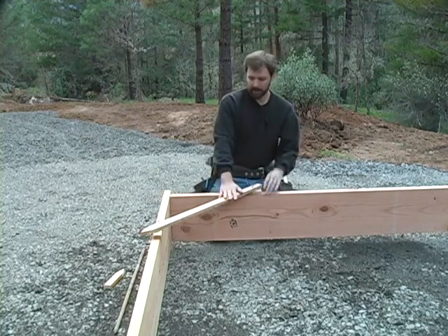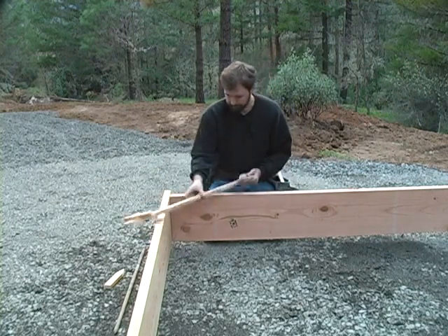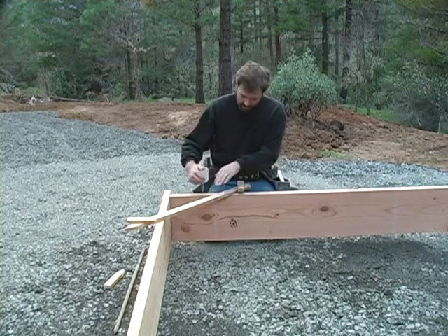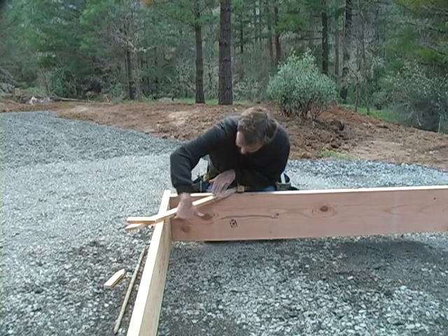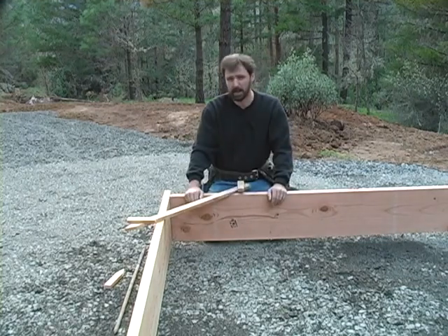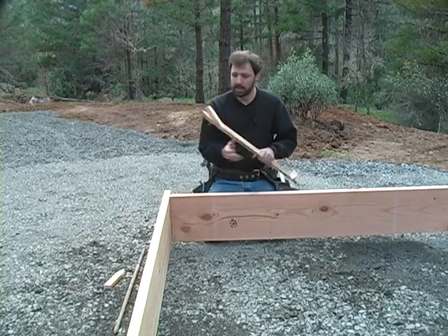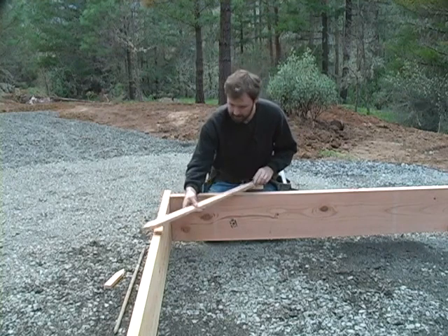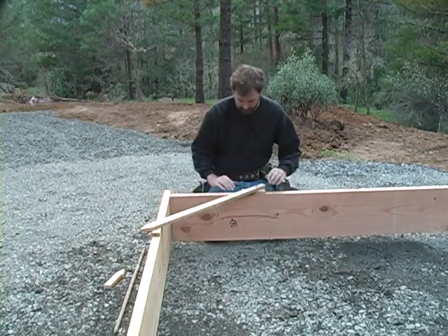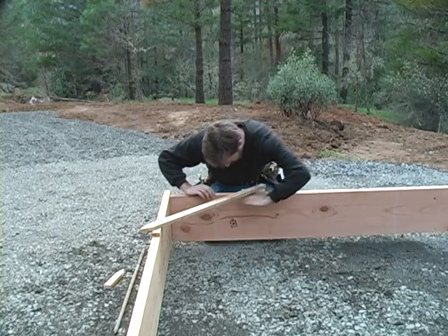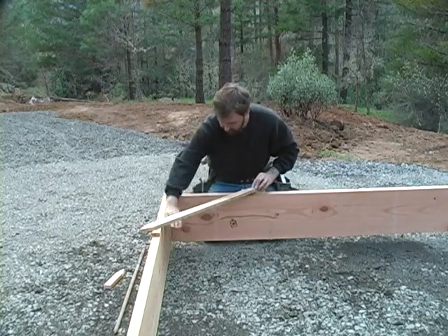Now if I take a regular stake here and just brace this corner flat like this, what happens when we fill this up with concrete is I can't get my trowel in here to finish off underneath this board, and I get a sore spot in the slab itself. So I just cut some pieces of the stake and set it up on top of that. That way, once I've got my concrete in here, I can leave this brace on and still come in with my trowel and get right under there and get a nice clean corner all the way up to the edge of the form.